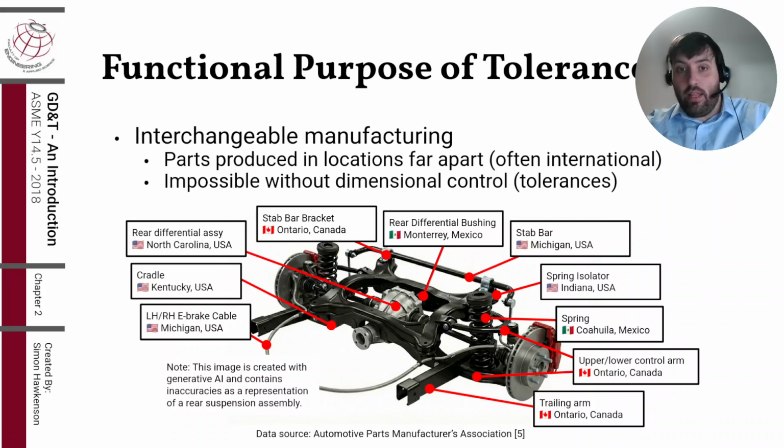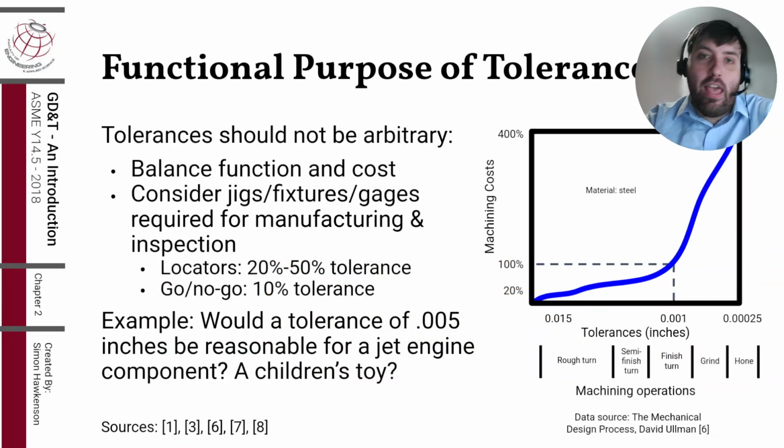So you might think then, let's just make our tolerances super tight and not worry about tolerances at all. Well, now your assembly costs 4 times what it should. Machining operations have costs. As you tighten the tolerances, the cost of machining your part increases exponentially. So realistically, you should set your tolerance requirements to be as loose as you can while still meeting your functional requirements.